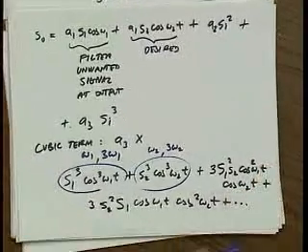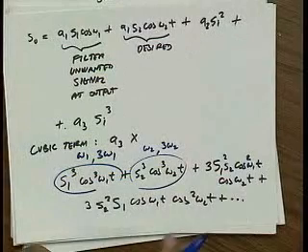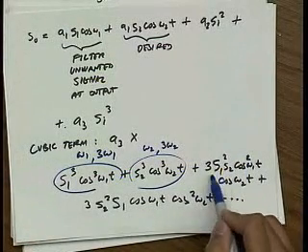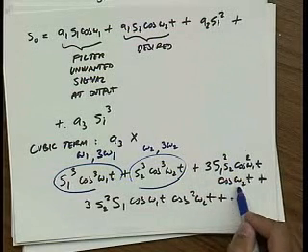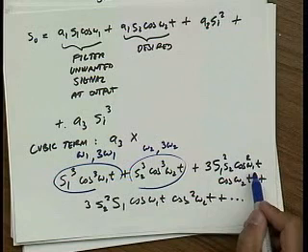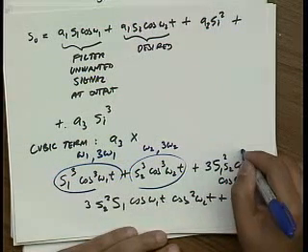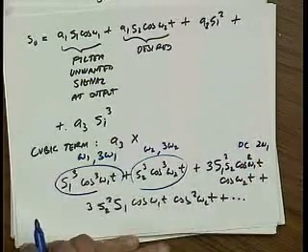All right? Look at this term here. This term is the nasty term. Why is it nasty? Well, remember, S1 is a big number. S1 is that big signal, and I'm squaring it. So it's even bigger now. And here I have cosine squared, which produces a DC term and a 2 omega 1 term.